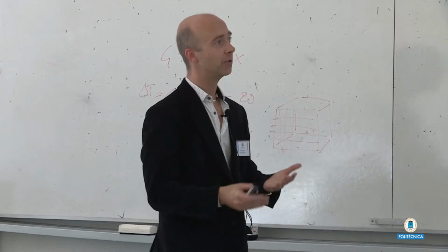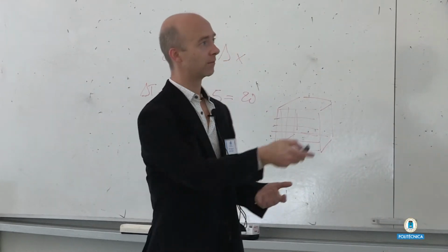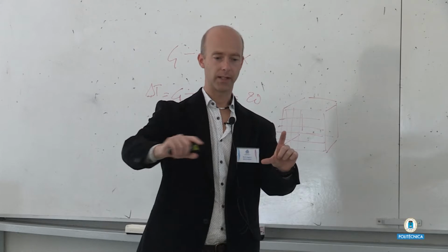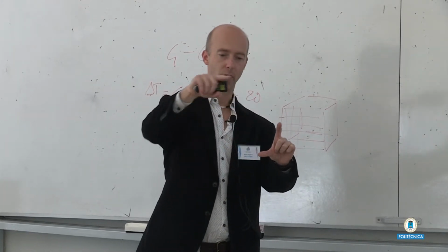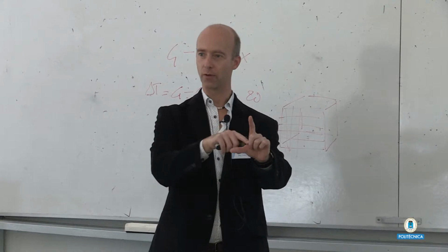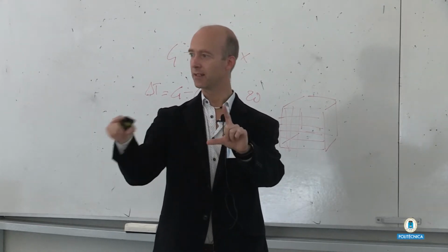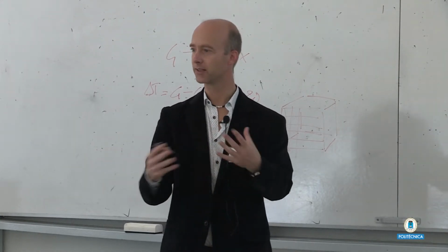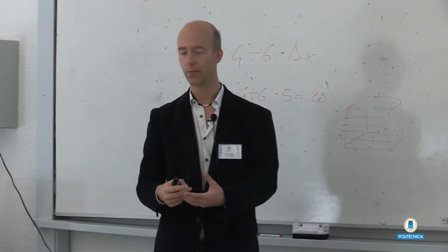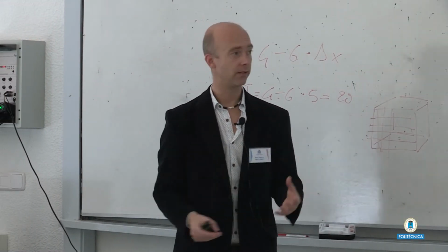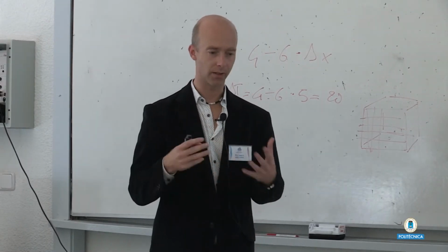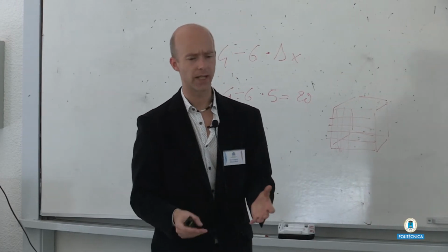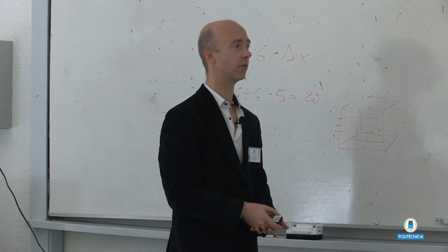So there are good reasons to go to a 2D model. Maybe the last one to say: if I have a meandering channel, then during low flow the flow path is around the bend, but during high flow I basically follow the inner bend. I flow over the floodplain, and that's the shorter path, and 1D models are not able to handle that well in general. You can tweak and use your knowledge of the details to make the predictions a bit better, but in general it's something to be aware of.